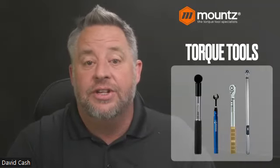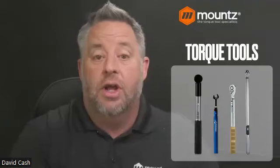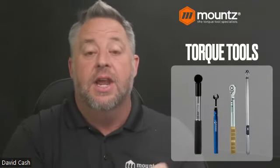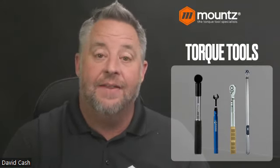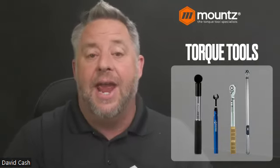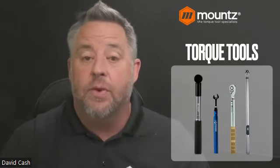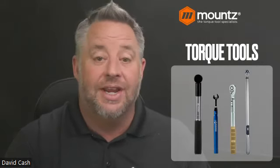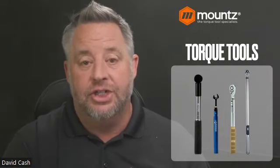The next style of wrench there is going to be a breakover style wrench. Now this wrench will allow us, as we use it, it will simply start to break at the pivot point. And once that has done that, that is the amount of torque that has been delivered at that particular value for that wrench. So the breakover wrench also gives us that ability not to over torque, gives us a really big signal that torque has been achieved.